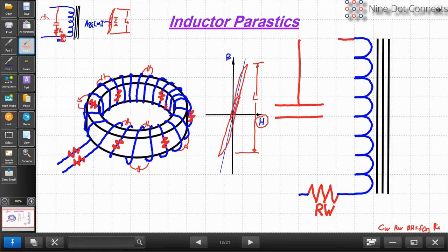And what does this give rise to? Well, this gives rise to the self-resonant frequency. And it turns out that this is also where there's another resistive constant that goes in here, if you want to use it, that has to do with some of the frequency-sensitive things. Obviously, at DC, what are you going to measure for resistance? You're only going to measure the resistance of the winding. Sorry, that's not RW.